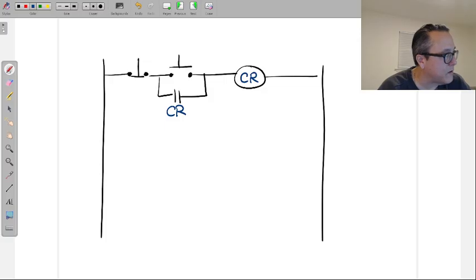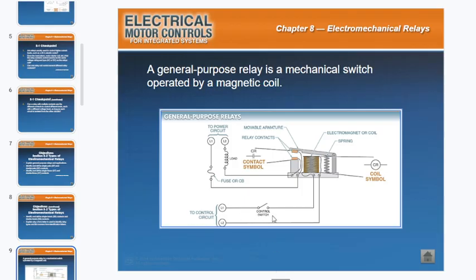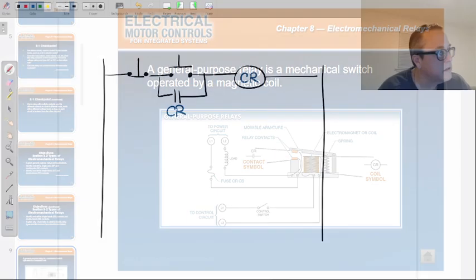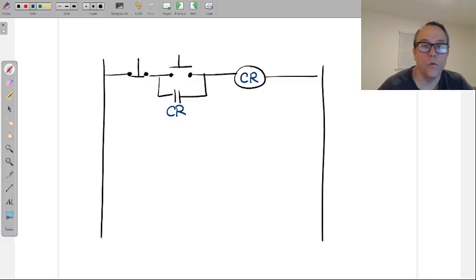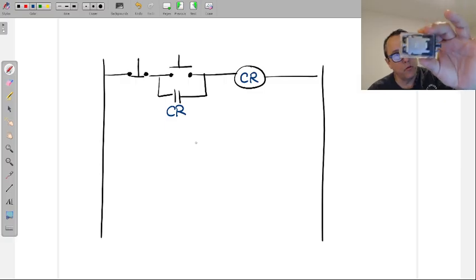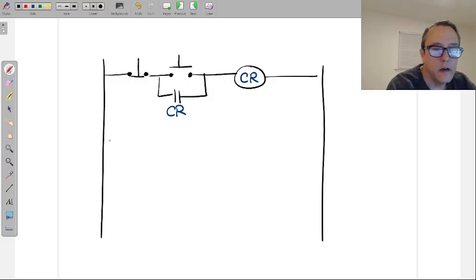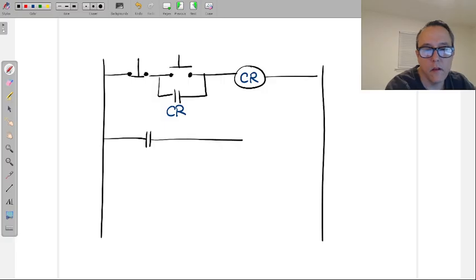Going back over to the diagram, just a little bit different from the one that they have here, where they're showing us the control circuit with that switch. That switch is being replaced with this push button setup, with the holding contact or seal or latching relay or latching contact. Now from here, we use another one of the contacts inside the relay on another rung to now energize the motor.